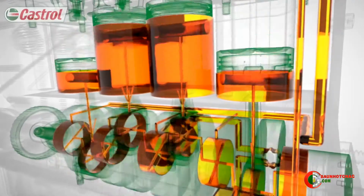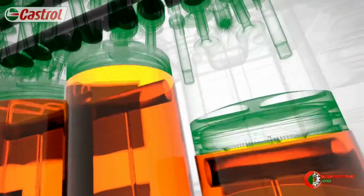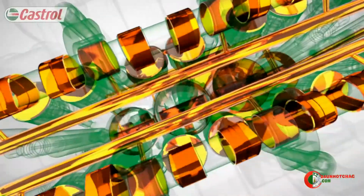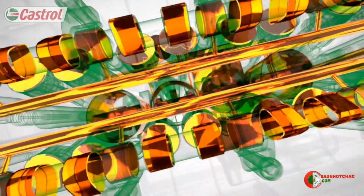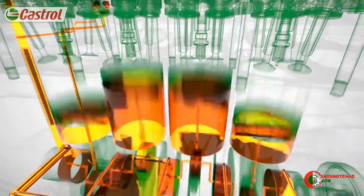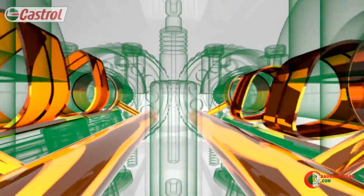The bearings, supporting the crankshaft on a continuous film of oil. Pistons, cooled down and kept clean by the oil's detergent action. And the valve train, protected by the oil's anti-wear system. Loads in the valve train are the highest in the engine. This is where the oil experiences the most stress. To avoid friction and damaging wear, these fast-moving metal components must be lubricated. The oil is the only thing preventing metal-to-metal contact.